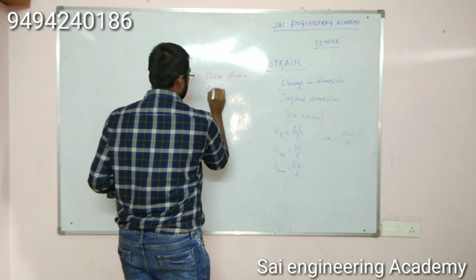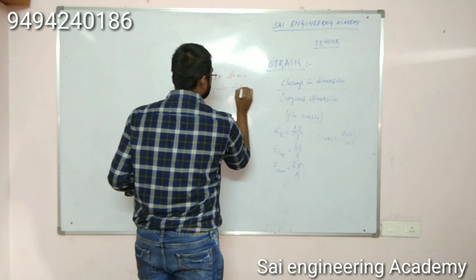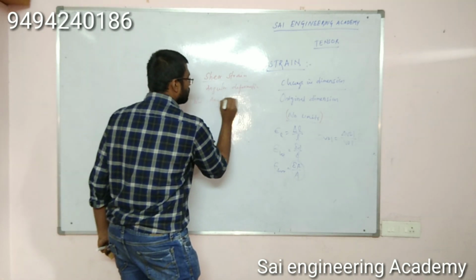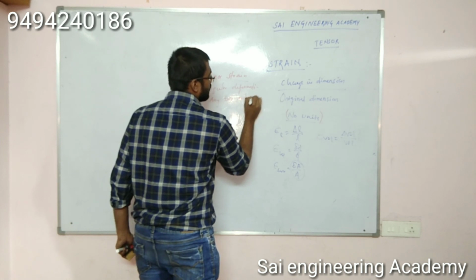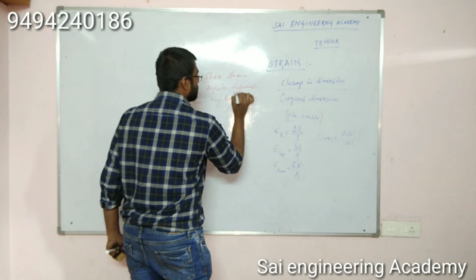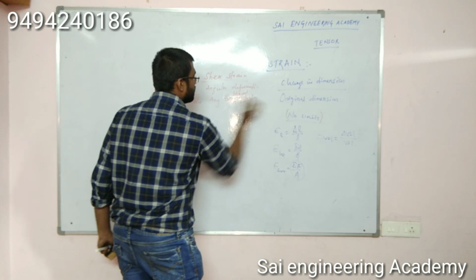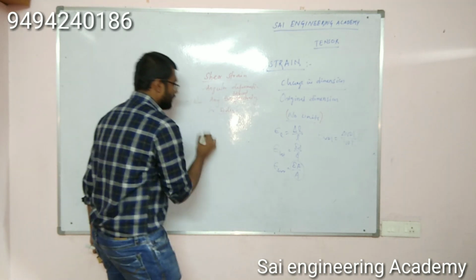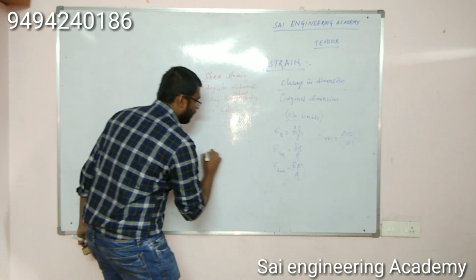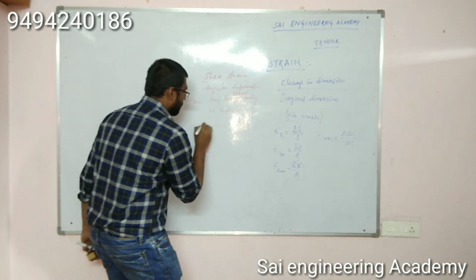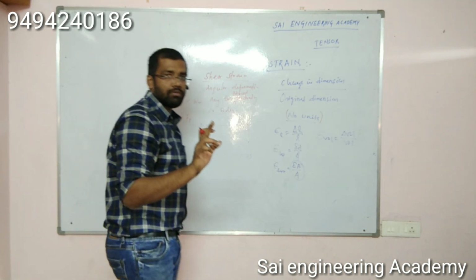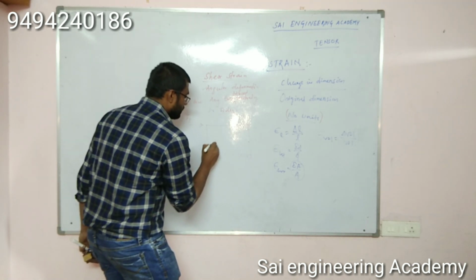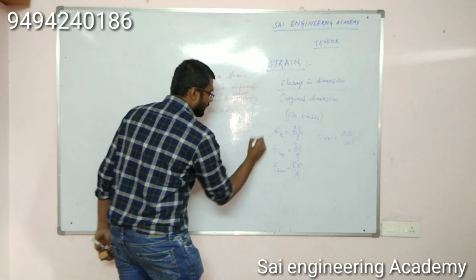It is the angular deformation between any two mutually adjacent, mutually perpendicular sides. So he has to satisfy these two conditions. You take a block which is fixed here and I am applying a load. Which force? Tangential force. Yes, shear stress. Then literally the layers will be moving like this.